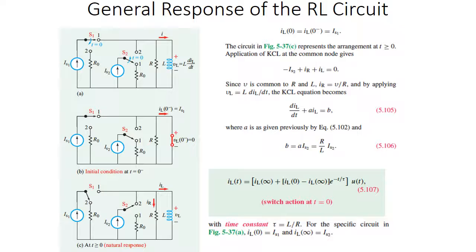The voltage drop over the L is slightly different than we've looked at before. V_L equals L dI_L/dt, so that's going to be the change in current over time. Like capacitors were to voltage, inductors are to current. So an inductor, when it's turned off, is going to be able to provide a little current to the system for a short amount of time as that magnetic field collapses.